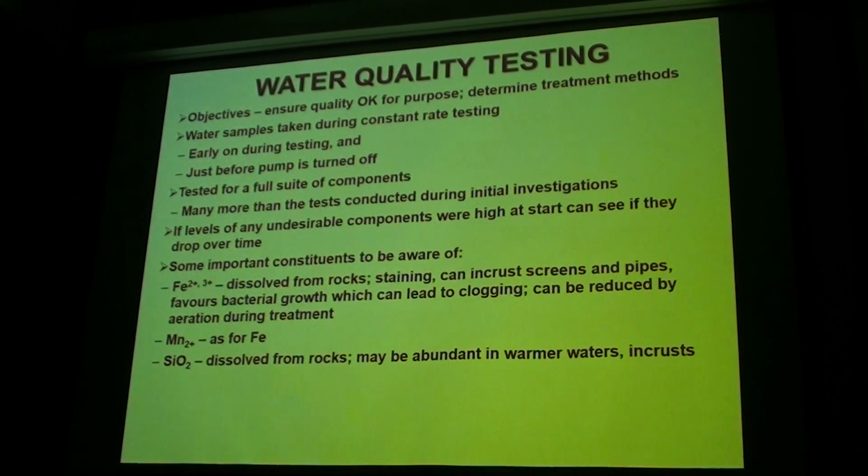Silica, dissolved silica again from rocks. In warmer waters you'll be able to dissolve all this stuff, and of course it precipitates out when the water flows through the screens and the velocity increases, pressure decreases, and it encrusts quite nicely as well, so it's something to deal with.